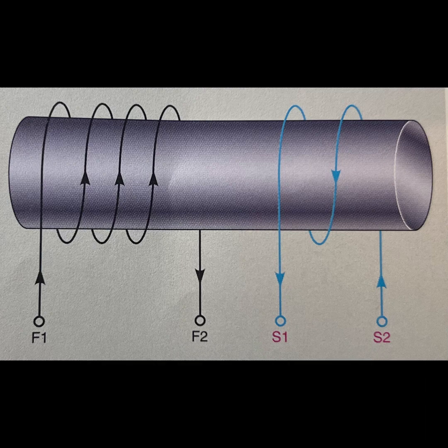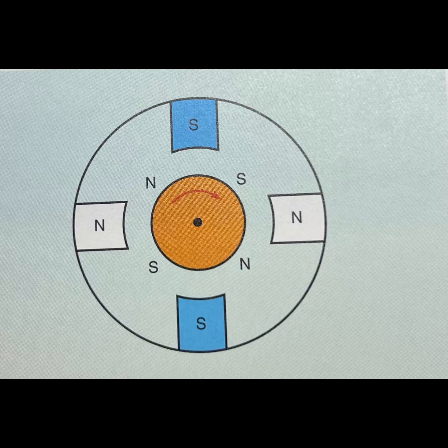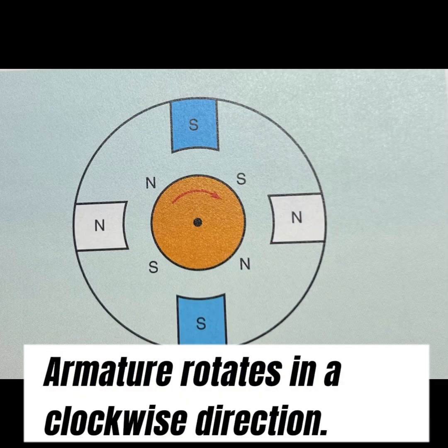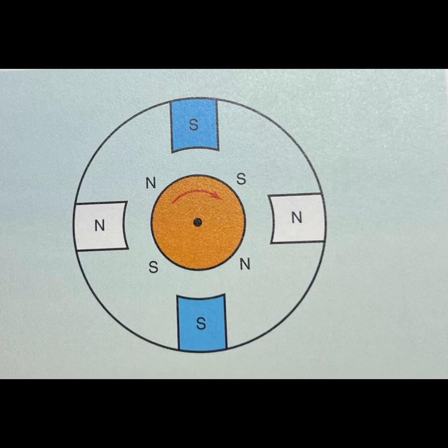Armature resistance is kept low, generally less than 1 ohm. This is because the speed regulation of the motor is proportional to the armature resistance. The lower the armature resistance, the better the speed regulation will be. Where the brush leads extend out to the motor at the terminal box, they are labeled A1 and A2.